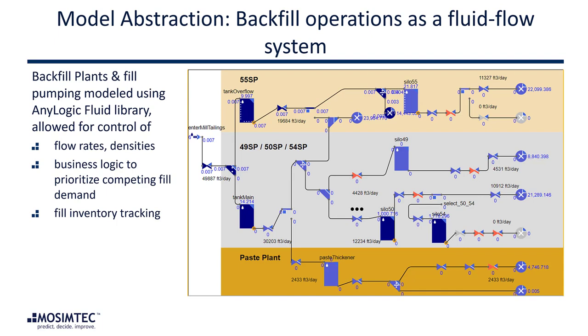The flow of tailings into the backfill system is based on mining rates. If the underground miners work faster, it results in more tailings to be generated, and that eventually flows into the backfill system. Any excess tailing that is not used for backfilling headings has to be purged into a tailings pond. So the goal of the backfill analyst is to manage demand for fill, current inventory in silos, and regulate flow to minimize such purges to the tailings pond.